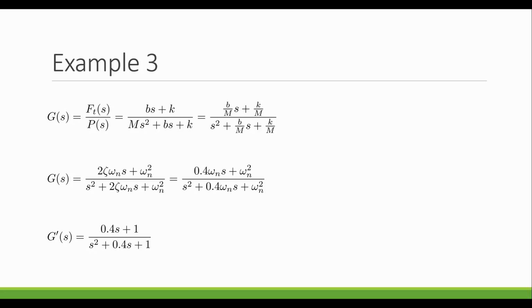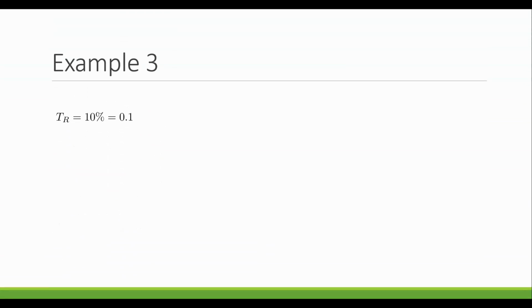But before I make the Bode diagram, what are we actually looking for? Why do we need the Bode diagram? Well, back in the problem statement, we were told that the transmissibility should be 10%. We want only 10% of the input force to be transmitted into the floor. So what does that actually translate to? Right, so that TR is 10%, which is also expressed as 0.1. So that is the linear ratio really that we're looking for. But in the Bode diagrams, our magnitude is by default going to be expressed in decibels. So I do want to make a conversion here to see what 10% or 0.1 is in decibels. So my quick conversion here, I went 20 times the log base 10 of 0.1, which is negative 20 decibels. So that is what we're going to be looking at once we make the Bode diagram.